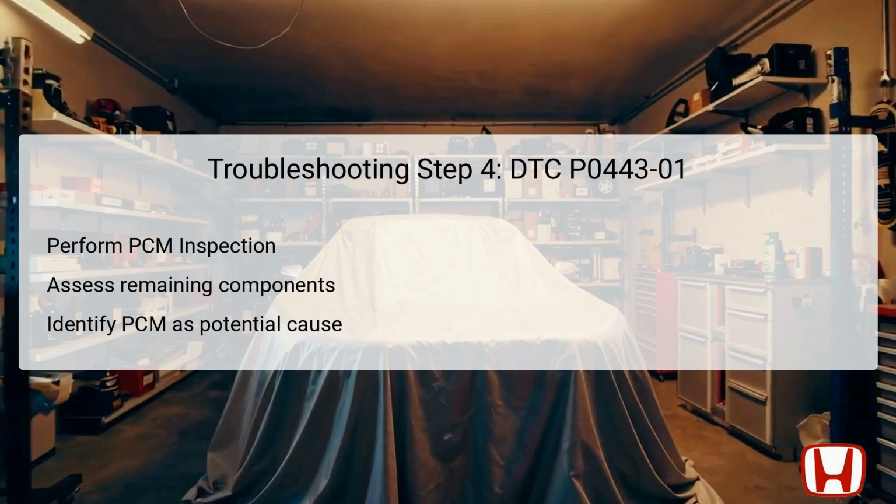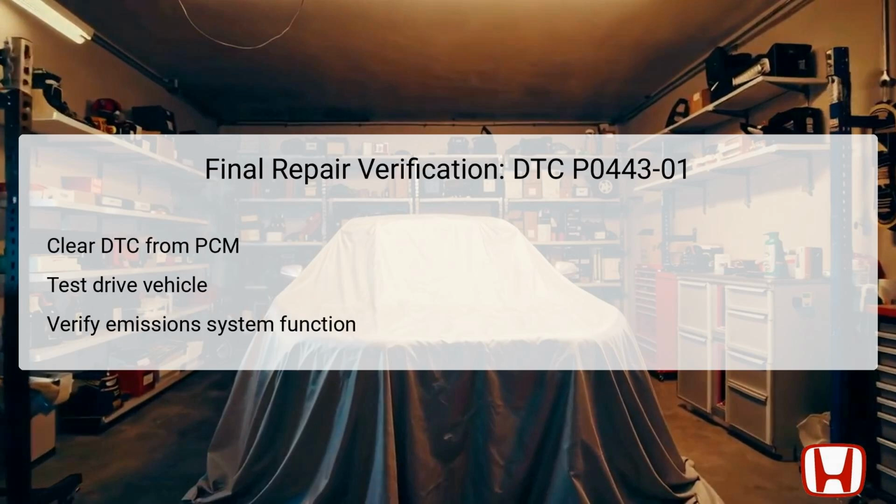Accurately diagnosing a faulty PCM is vital to ensure proper communication and functionality throughout the vehicle's electronic systems, particularly regarding emissions control. Once all troubleshooting steps have been effectively completed, it is vital to perform a final repair verification regarding DTC P0443-01. Start by clearing the DTC from the PCM to reset the vehicle's diagnostic monitoring processes. Following the DTC clearance, conduct a test drive under various operating conditions to assess vehicle performance and ensure the proper functioning of the EVAP system.